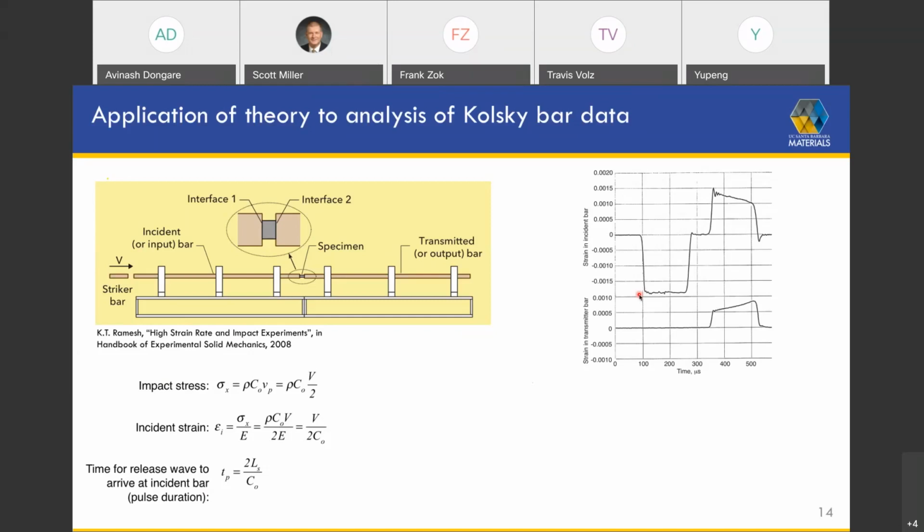For example, at very low stresses and long times, you can get vacancy diffusion or self-diffusion between grain boundaries. This is the so-called Nabarro-Herring or Coble creep type mechanisms. And these mechanisms are slow. Transporting matter by diffusion is very slow.